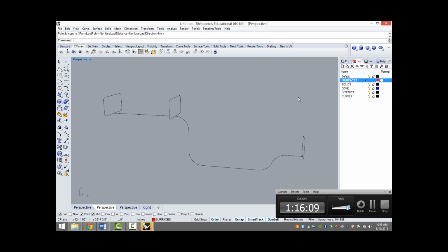What was that? Just copy. So, good question. I'm going to type in copy, select objects to copy, enter, and then I'm selecting at midpoint. Okay. And then it's clear that between this form and this form, we're changing scale, right? And we could even be changing orientation, as Elliot was saying. So these two frames or profile curves don't recognize the change in scale that would happen along the rail.